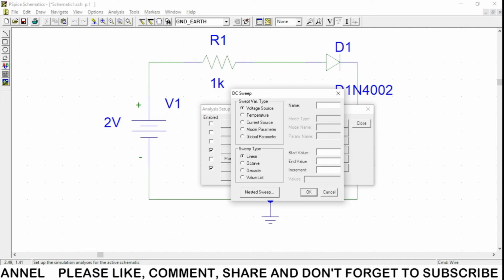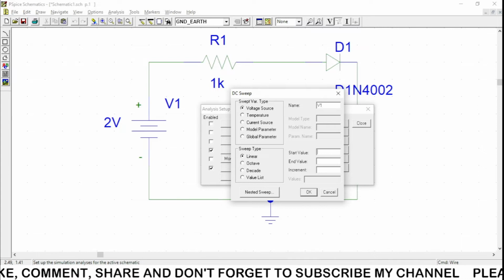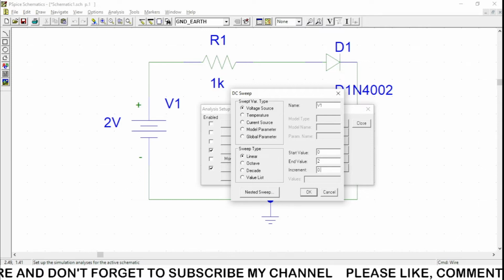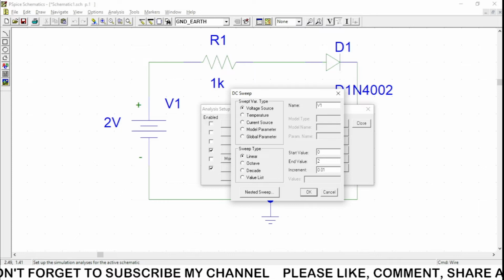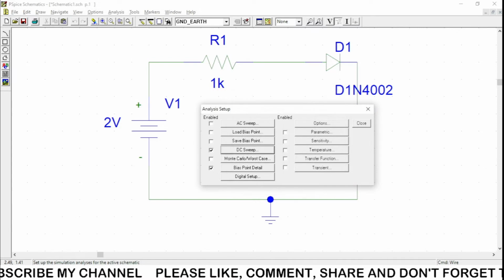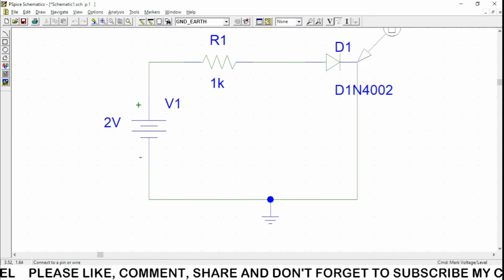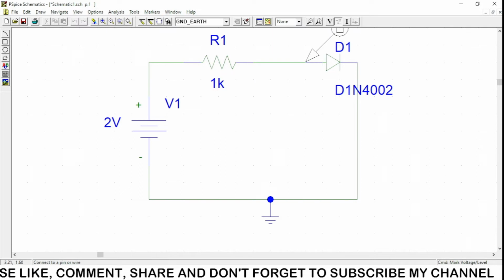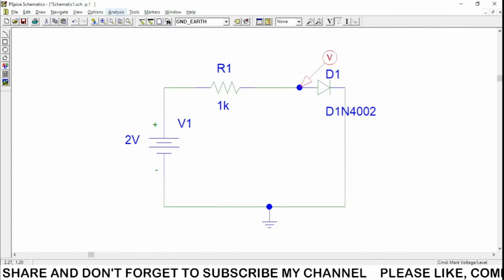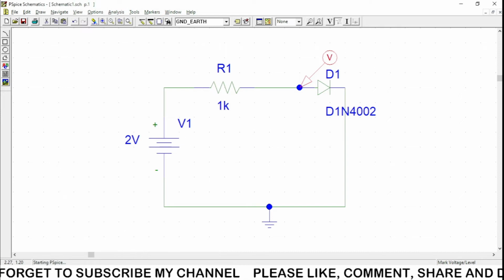So I'm going to take a DC sweep with voltage source V1. We are going to start V1 at 0 volt, with an ending value of 2 volt, and it should start with an increment of 0.01. Okay, you can give the voltage over here also. I'm going to press OK in here, close. If we need to find out the current direction, we can place a voltage marker over here, so that the graph will be drawn according to this particular part. So analysis, simulate, there is no error, no warning, all things are good.